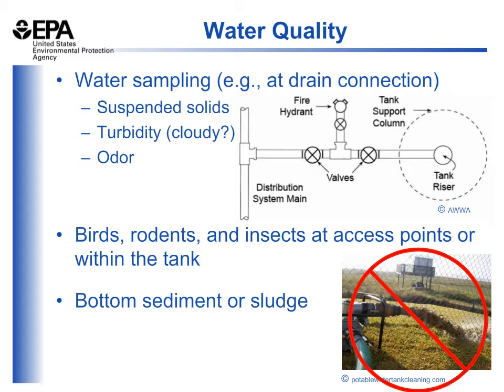And the bottom or the last few feet of water in your tank should be pumped to waste using portable pumps or a vac truck or other methods. And again, the disposal of the sediment at the bottom of your tank may be subject to local regulations that could require you to first dechlorinate the water or remove it to an appropriate site. Again, you're going to want to check with your local environmental officials.